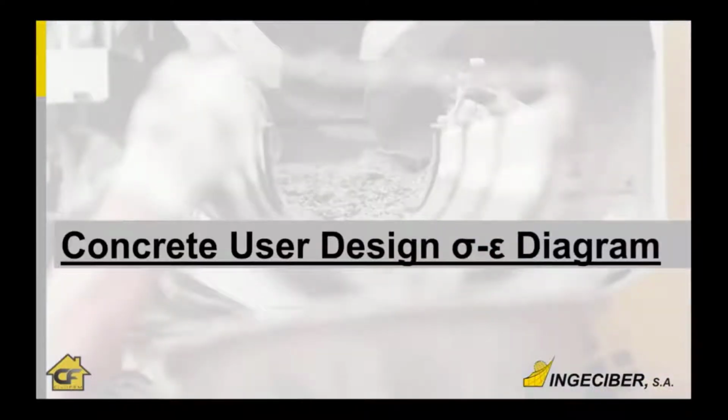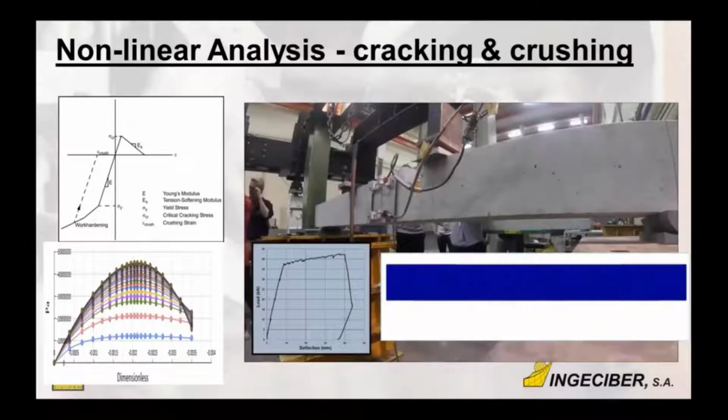Well, we are going to start with the concrete user design sigma-epsilon diagram. Just before seeing that, I will give an update of what CivilFEM already has for concrete. In the concrete, we have the diagram for analysis and also for design. For the analysis, at the solution level, they are for nonlinear analysis.